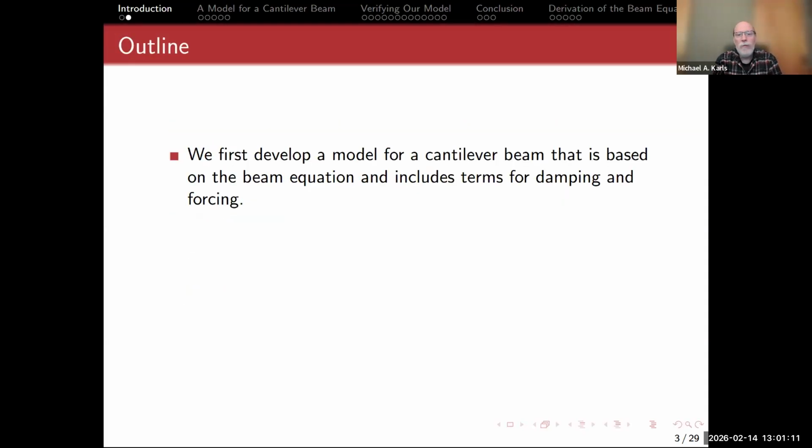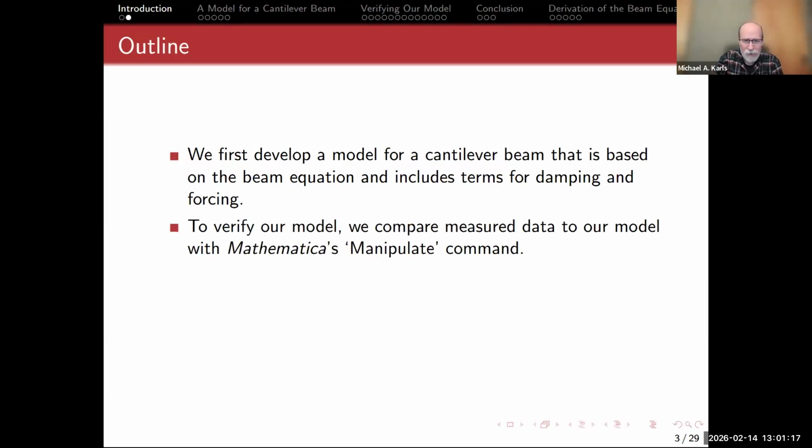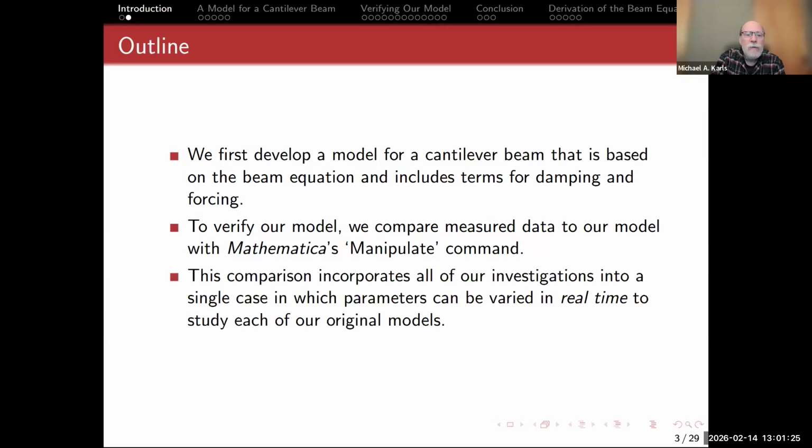Okay, so we're going to first develop a model for a cantilever beam that's based on the beam equation and includes terms for damping and forcing. And then to verify our model, we're going to compare measured data to our model with Mathematica's Manipulate command. And this comparison incorporates all of our investigations into a single case in which the parameters can be varied in real time to study each of our original models.